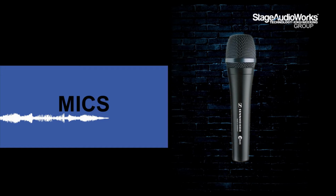Right, so we're going to start with mics. We're talking about a transducer that converts energy from one form to another, namely acoustical energy, which are sound waves, into electrical energy, which is the audio signal. Different types of mics have different ways of converting energy, but they all have one thing in common, which is the diaphragm. This is a thin piece of material such as paper, plastic, or aluminum that vibrates when it's struck by sound waves. The diaphragm vibrates, causing other components to vibrate, and those vibrations are converted into electrical current, which then becomes the audio signal.